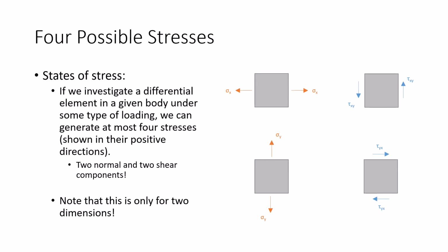So first off, if we look at these stresses over here, they are not in equilibrium. Why are they not in equilibrium? Well, the same stress going up equals the same stress going down, but this wants to rotate the section, right? It is a stress couple. One's going up, one's going down.